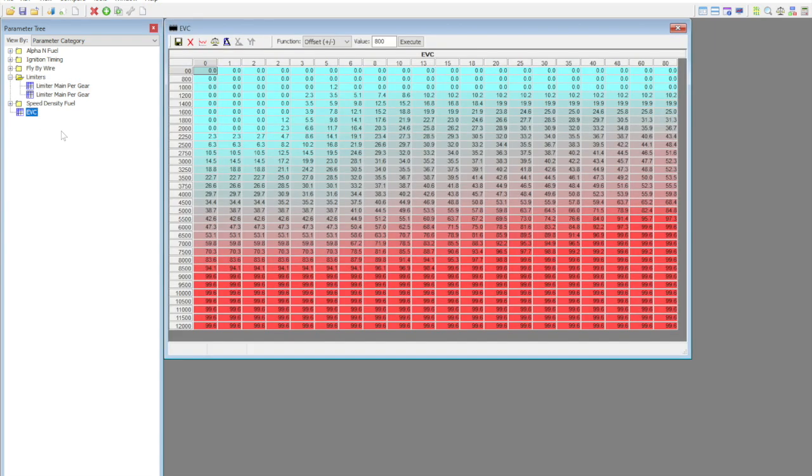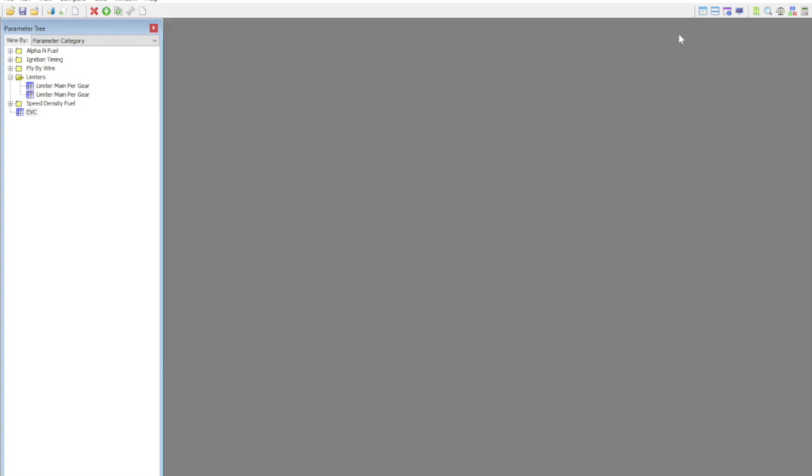Of course, the exhaust valve mapping, servo mapping. Most exhausts eliminate this exhaust valve, so it's not even relevant, but it's there in case you want to see it. As throttle goes up, exhaust valve starts to open. As RPM goes up, exhaust valve starts to open. Pretty cool stuff. You could use this on a stock bike with a stock exhaust to kind of tune in how loud you want the bike to be. So we kind of went over the basic mapping.